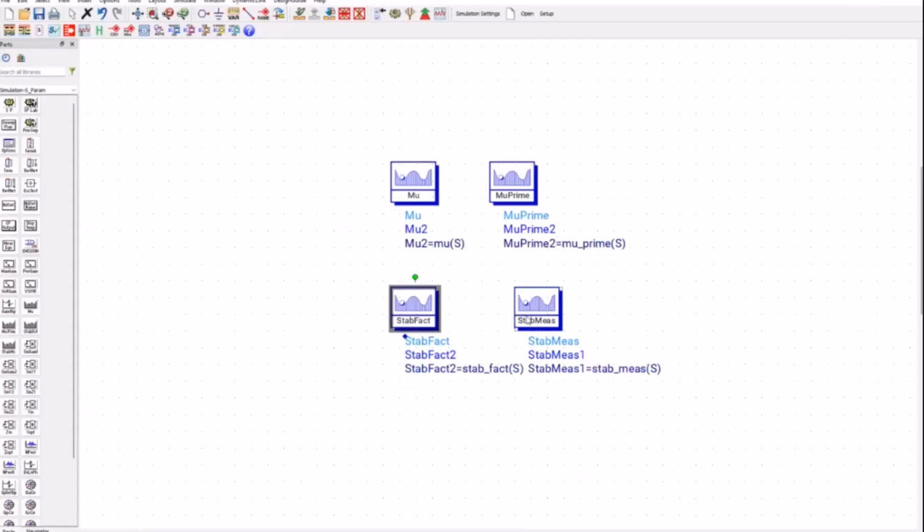Now, since LNAs are low power circuits, low power stability like stability factor, stability measure, mu prime is sufficient. If you are doing power amplifier design, these are the starting points, but they do not reflect the right condition when your device is operated at a very high power.